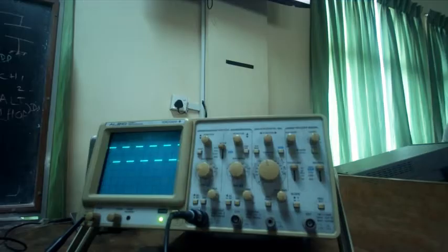It's a calibrated signal. It says sometimes 2 volts peak to peak, 1 kilohertz. Sometimes it says 0.5 volts peak and 1 kilohertz or 10 kilohertz or whatever it is. You check your oscilloscope, it will say that. So it guarantees that that's the signal that comes out of it. It's a square waveform, just like this.